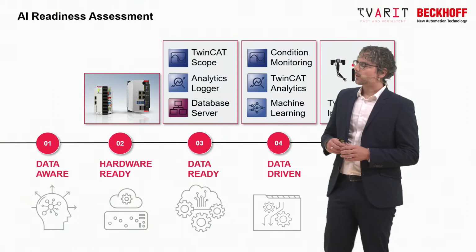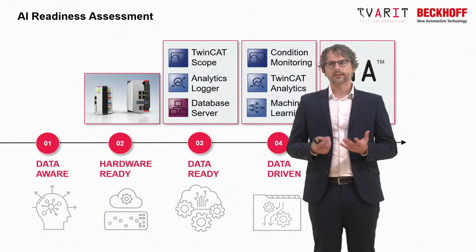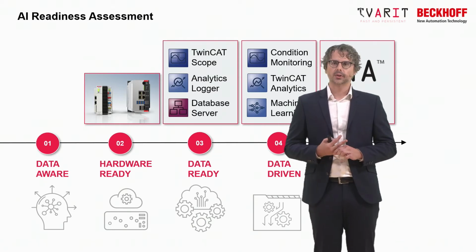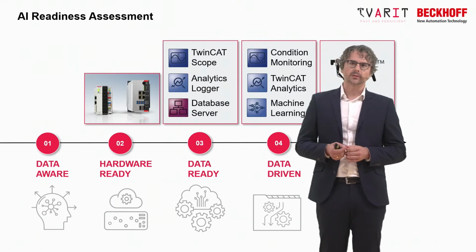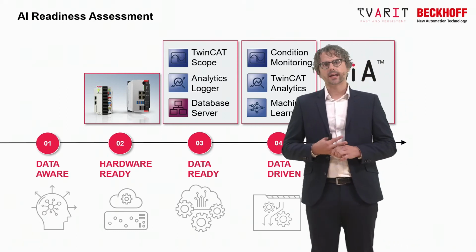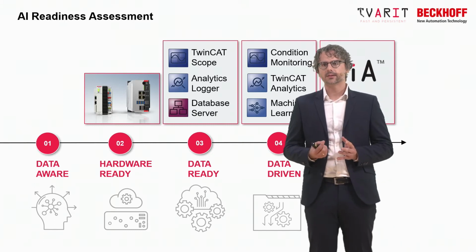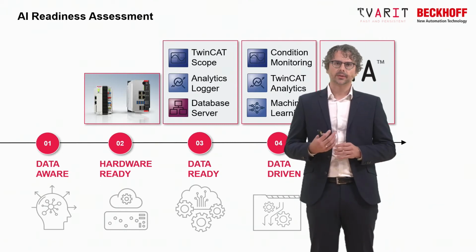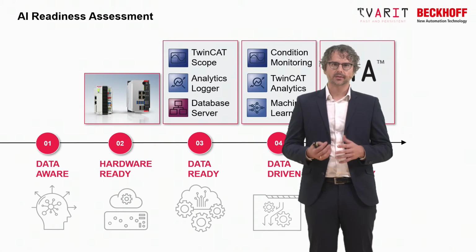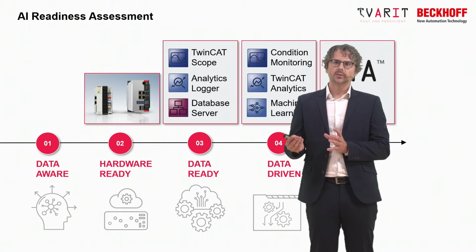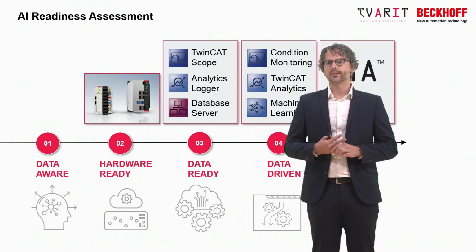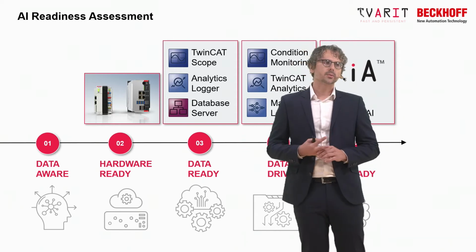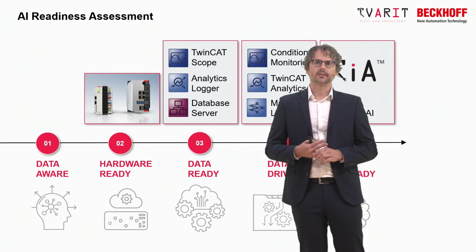Data ready. So we also, of course, offer you the tooling, the flexible products to get the data out of your controllers. For example, the database server, already years in the field and still being used in many, many applications, connects you directly from the PLC to a database of your choice, for example PostgreSQL or MySQL or MS SQL, it doesn't matter. You choose your database, and we offer the interface using the database server. And then you stream directly from the PLC into an SQL or even a NoSQL database.